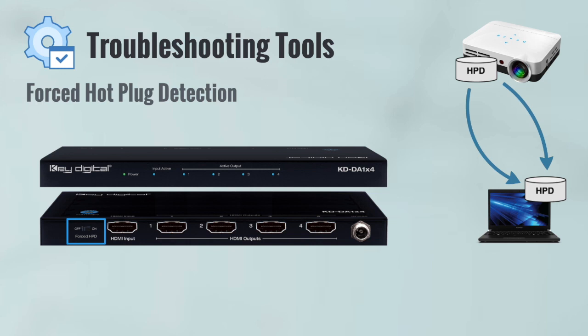So Key Digital products with forced hot plug detection, once again including all of the distribution amplifiers discussed here, give you the option of forcing the hot plug detection voltage to an active setting, high voltage if you will, or when turned to the off position, allowing that hot plug detection voltage to pass through our system as normal.